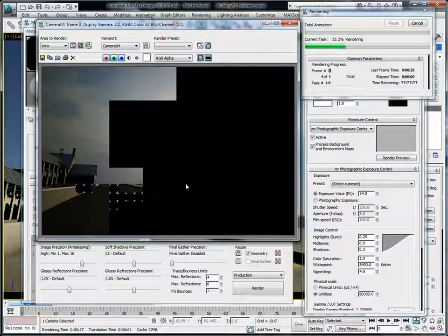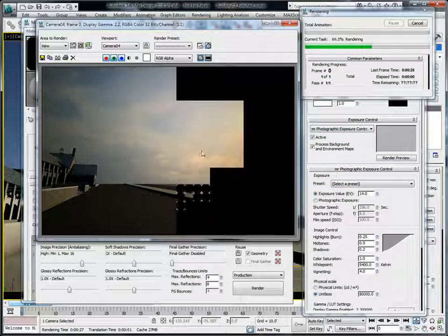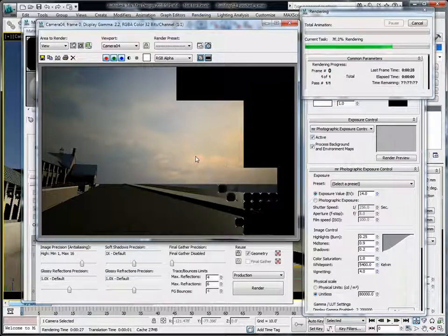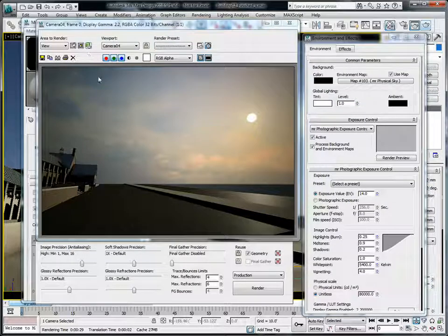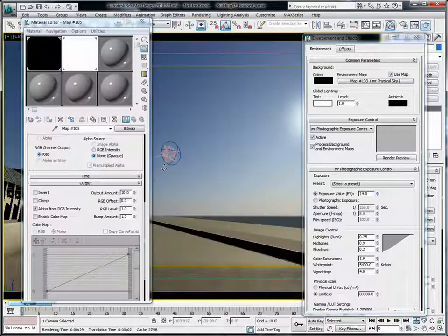And the neat thing about this, of course, is that the mental ray sun is actually tinting this cloud, because as you know from looking at the image before, the clouds are basically white, but once it gets over here to this section, you'll see that it's kind of an orange tint, and that's coming from that mental ray sun here. Now once the sun gets up around noon, and that light becomes white, or if I come in and manually change it to white, it will not produce this orange, so you can get your white clouds, or neutral colored clouds, back.